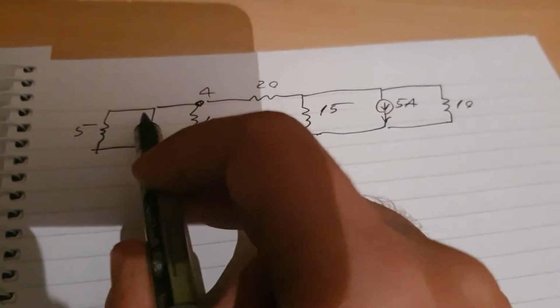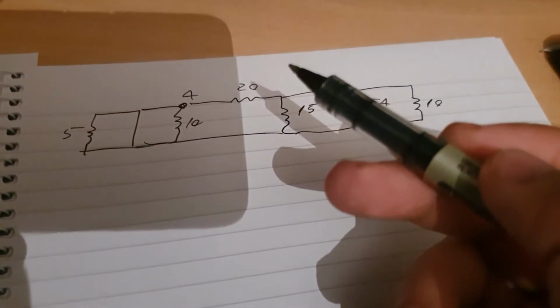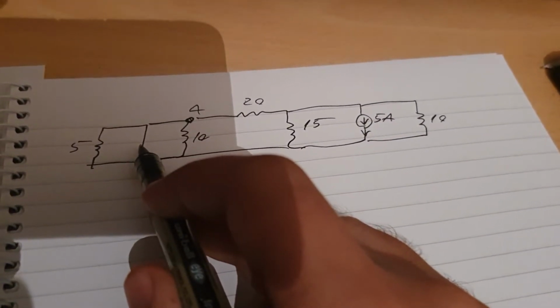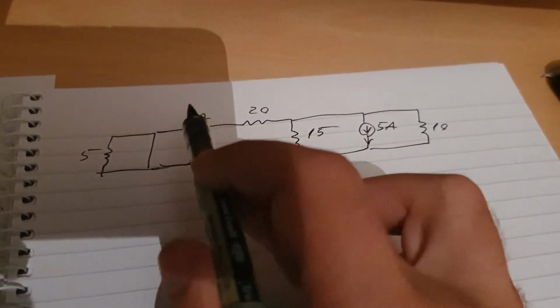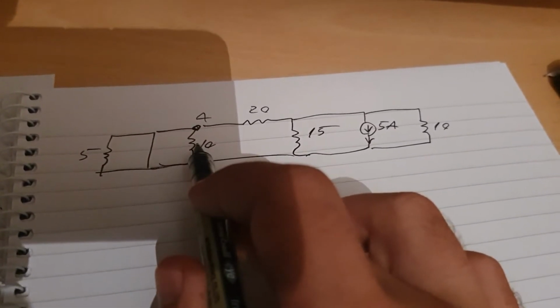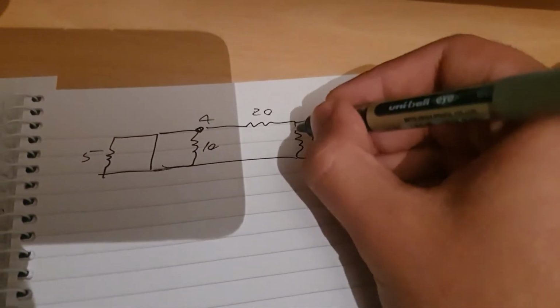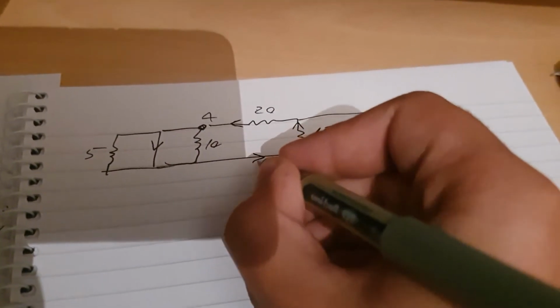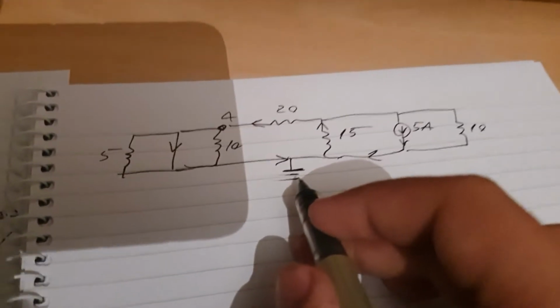But here's the interesting part. Now, as you can see here, there's no resistance in this wire, yes? That means this is a short circuit. And theoretically it's a short circuit. So all the current is going through this wire only. Even though these three are in parallel, only this wire is getting all the current. So the current will go in this direction, and it will go here and here to the ground, which will make all of them in series. Interesting, isn't it?